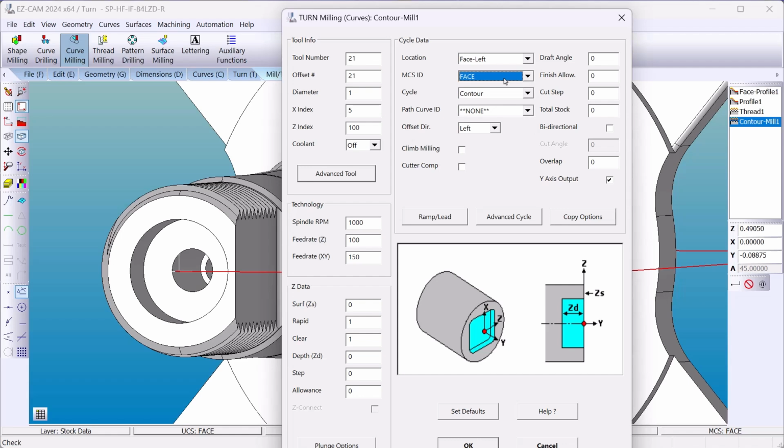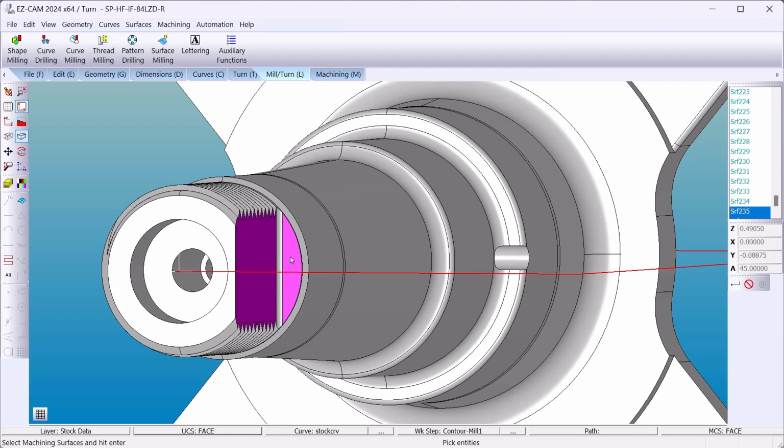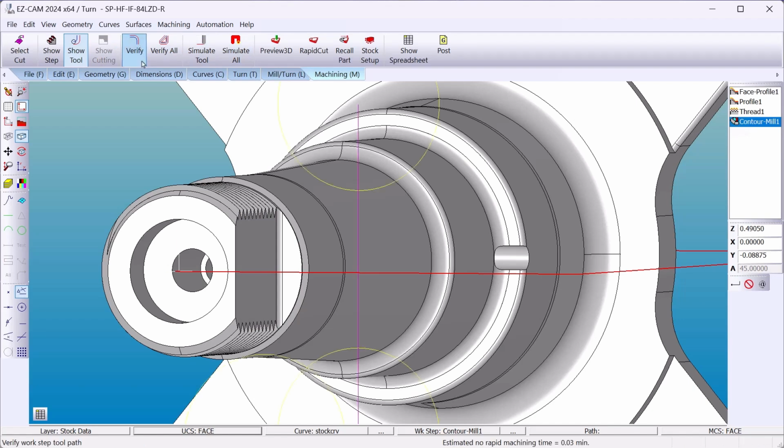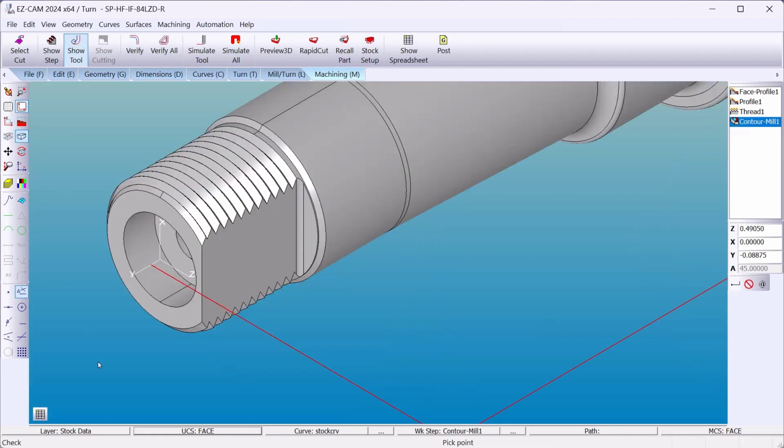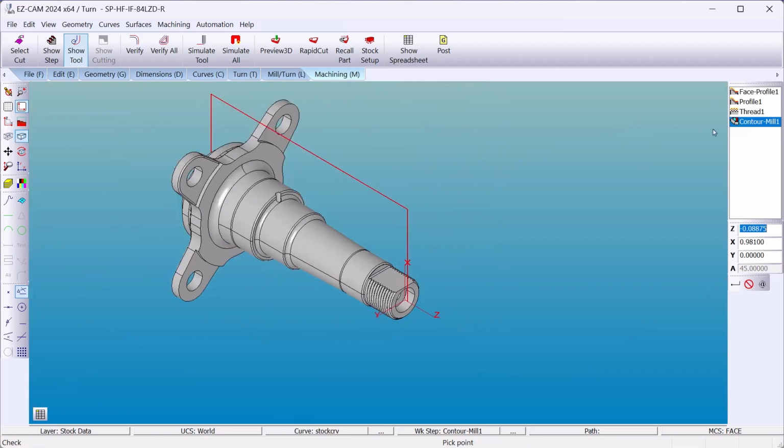In our coordinate system, now you can check y-axis. It's as easy as that to go from a rotary axis to the y-axis. We'll go machining, select cut surfaces, that face, and the bottom face. We're machining to this face here. Just go back to the world coordinate system. There. Makes it easier to look at the part. And we'll just right click and simulate from here.